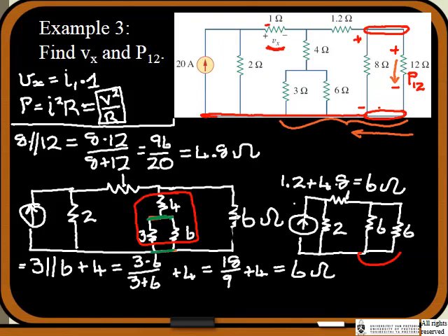But for that we are going to go, we've run out of space. No, we're not out of space yet. Let's finish this one as well. So what is 6 parallel with 6? Let's just draw a line there. And this is a neat little trick that you're going to find out, because what you're going to have now is 6 times 6 divided by the sum of the two, which is 6 plus 6.